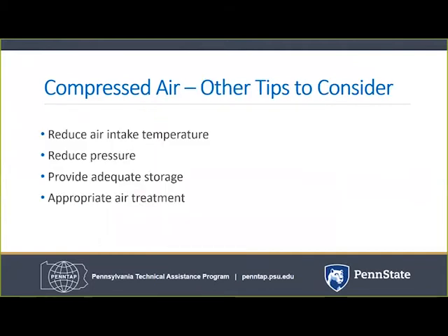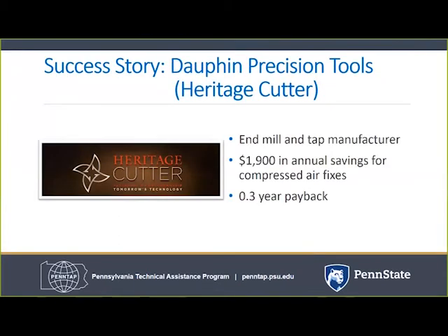There are other steps you can take to reduce the energy demand and cost of providing compressed air. You can reduce air intake temperature, reduce pressure, provide adequate storage, and apply appropriate air treatments. Investments in managing your compressed air pay off quickly.